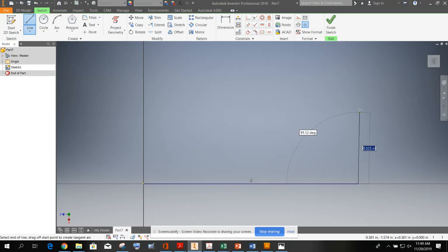I'm going to go up, I don't know, about that far. That far, go across, and then up. I want these to be 90 degrees, so I'm going to click when it says 90 degrees. I want those two to line up. Now, if I line them up like this and click, that means those two points are going to be on the same horizontal line forever. I want that to happen, so I'm going to go ahead and do that. Same horizontal line. And also line that up there and finish where I started.